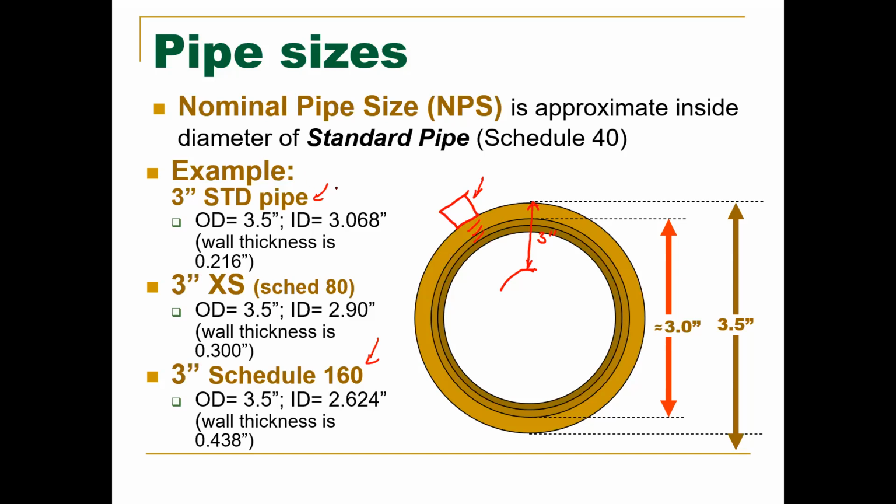If you ordered Schedule 40 piping, I think my chief engineer would have just tossed me off the boat in multiple pieces for replacing 3-inch wall thickness. The reason we had to start doing that was because we started busting holes through our piping. Again, in 6 months, we lost 3 inches of wall thickness due to sandblasting, just moving sand from one spot of the ship to the other.